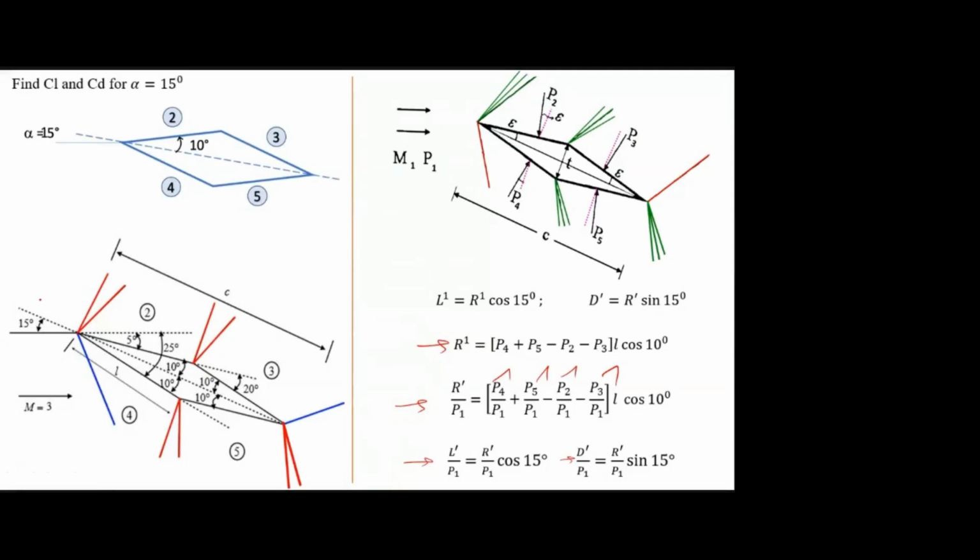And you know, across this is station 1, 2, 3, 4, 5, right? So across stations 1 and 2, P naught is constant. Across stations 2 and 3 also P naught is constant. Is that correct? Yes. And across this oblique shock, P naught is not constant. And here it is constant. So this is the general condition. With that, we have to find all these ratios: P2 by P1, P3 by P1, then P4 by P1, then P5 by P1.